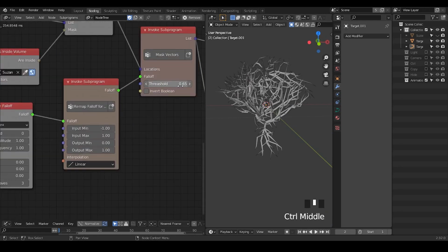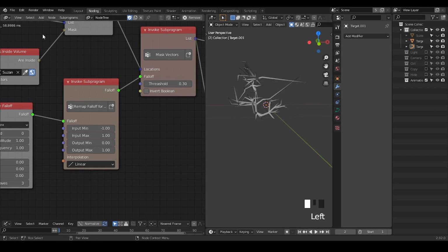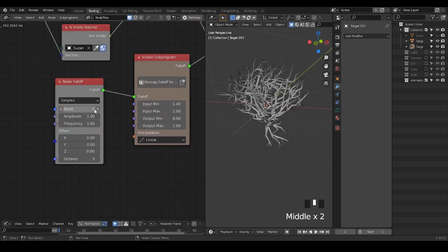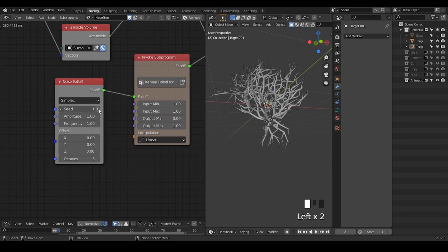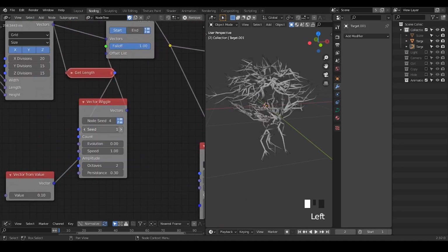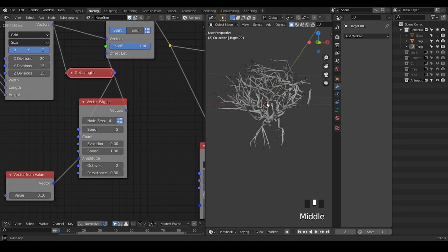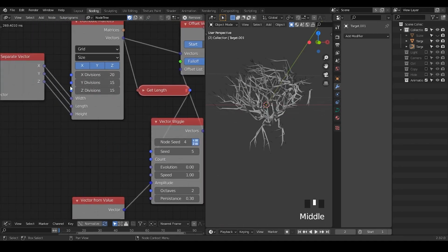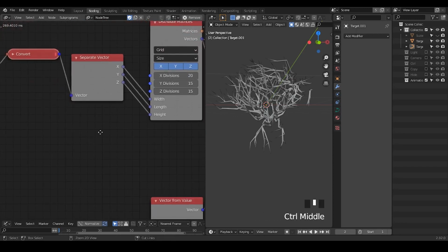Another is the threshold. You can increase the threshold to the right side so that more points are included. If your computer gets stressed, you can decrease the amount of points, but you also lose some resolution. So 6.0, 6.5. You can also increase the frequency, change the seeds. So there is change which minorly affects your results. Other changes might largely change your results. And last thing is resolution. Just always be careful with your execution time. Save your progress while you're working, which is very important.